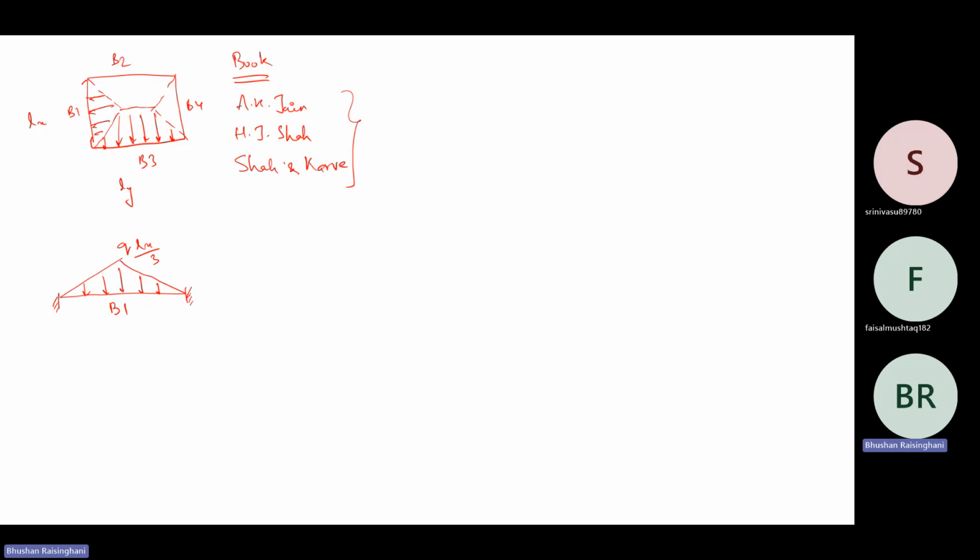So it will be fixed on both ends, and B1 will be the beam with length L and EI. Okay. And from this you will get a reaction, right? Vertical reaction will come, and also the moment reaction will come. These two reactions will be transferred to your two columns on which the beam is supported, right? So it became a frame for you for a particular story.